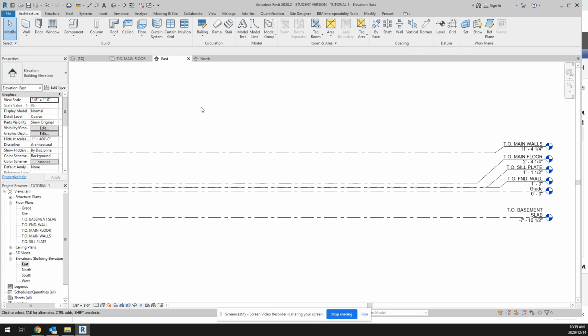So if I go to my floor plans, again, always make sure you're working in floor plans, that you're not working accidentally in structural plans, because see if I put structural plans down, you'll see that I have some of the levels, not all of them, but some. Make sure that you're always working in floor plans. Ceiling plans, sometimes people mistakenly start working on ceiling plans. Again, we don't want that. So always minimize everything that we're not using so you don't accidentally select things.